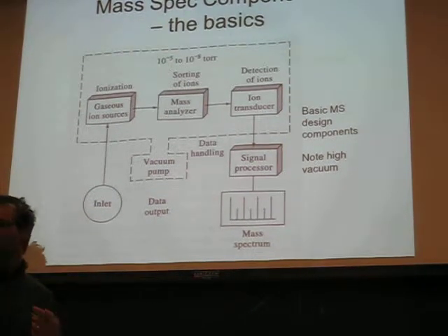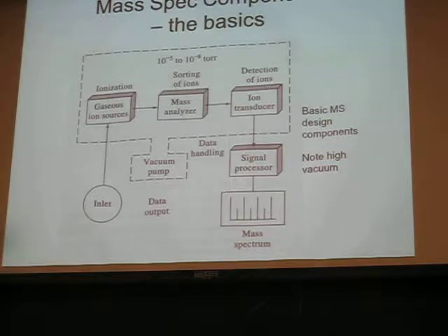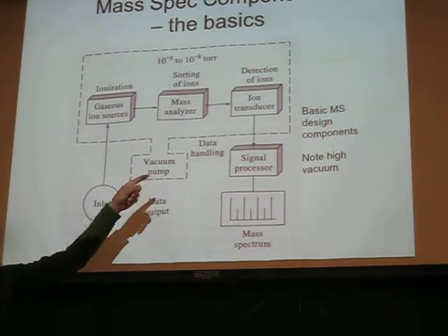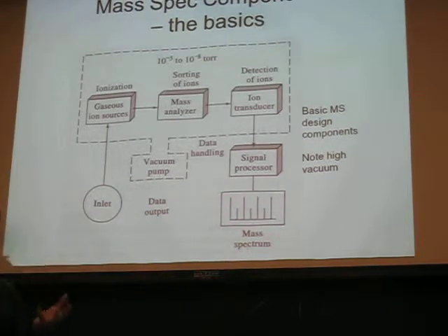In fact, when you load samples into the mass spectrometers, you start the vacuum system, and because parts of the instrument have been exposed to the atmosphere and there are oxygen molecules from the atmosphere adsorbed on the surface, not even condensate, just gas molecules, you have to start the vacuum and come back about 8 hours later for it to finally pump that gas down to a low enough vacuum. And so a big cost of the higher-end mass spectrometers is establishing these multi-stage vacuum systems to pump down to extremely low vacuum.